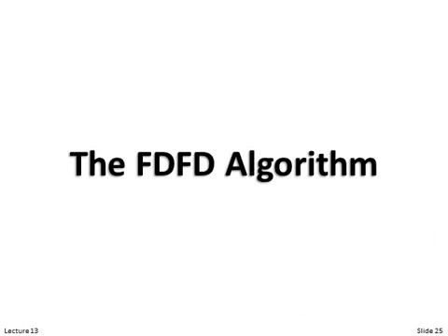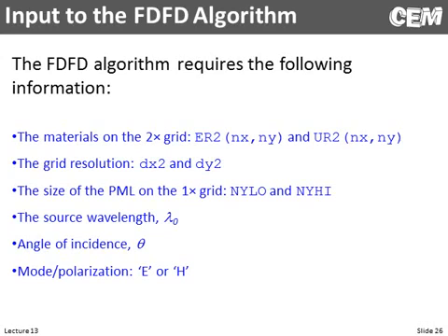Now we're in a great position to start all over again and talk about the finite difference frequency domain algorithm one little step at a time. And that's what this section will do. First of all, we have to prepare all of the data that our FDFD algorithm will need to run.